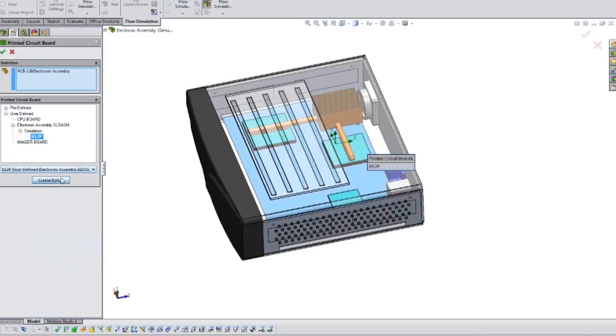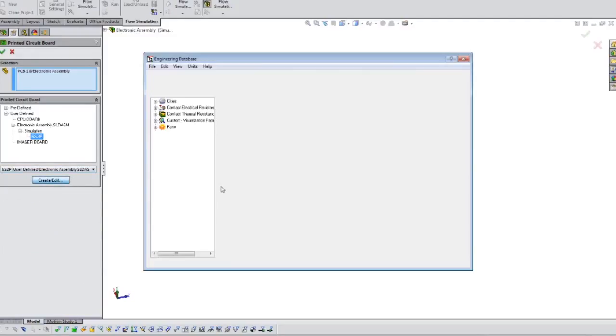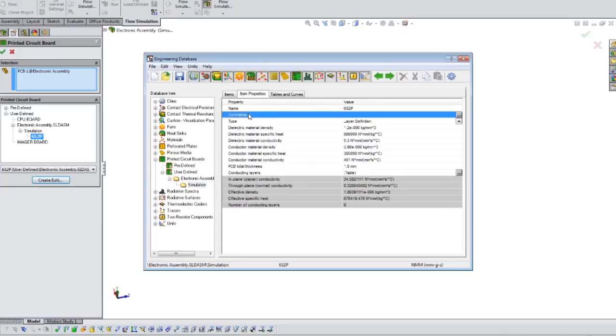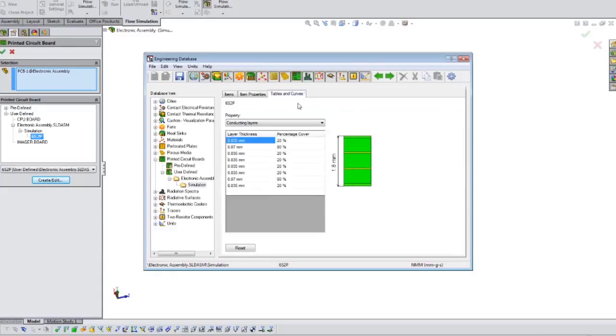So if we start from the top to the bottom, we can take a look at how a SolidWorks Flow Simulation project gets set up. And how this is all set up is using our SolidWorks Flow Simulation wizard. So I'll start it up here, and you can see when we start walking through the setup of a problem, it's a really easy and simple setup. Basically, if we look at how this problem is set up, it's an internal analysis. We've turned on heat conduction in the solids, meaning that in addition to solving the fluid flow problem, it's also going to solve the conduction problem.